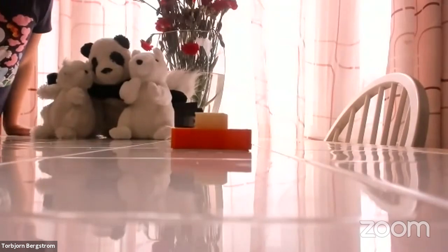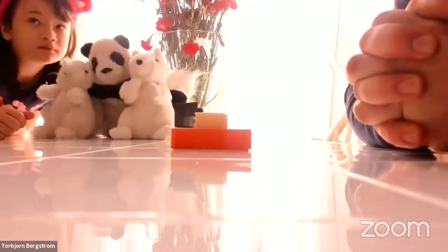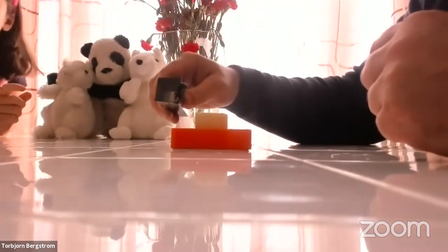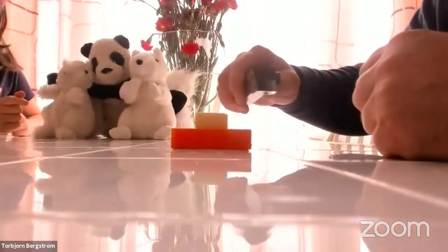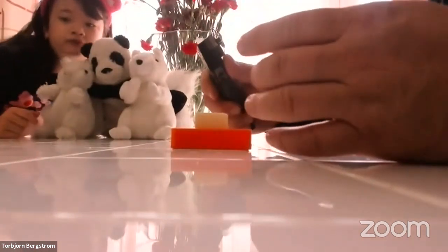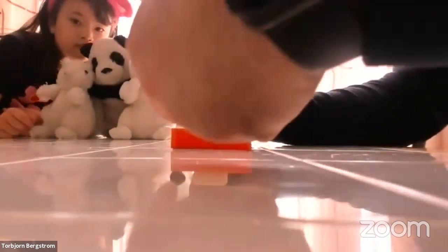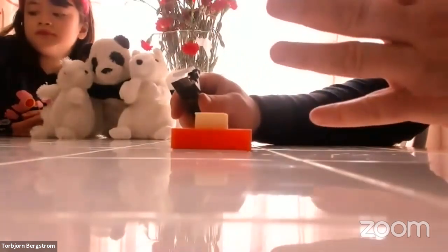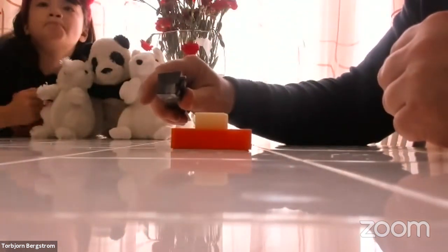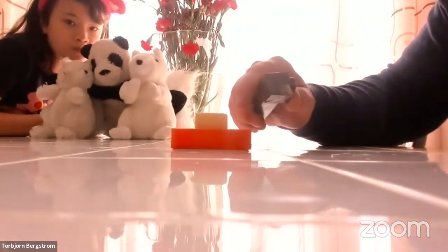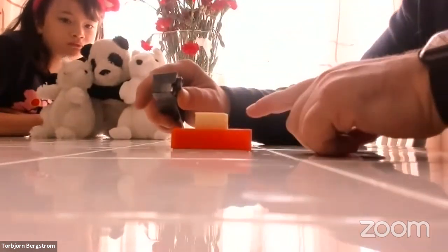All right, and you see Emily? Yes. Perfect. All right, so now when I move the tool up and down, I'm changing the uncut chip thickness. When I move the tool this way, this velocity that I'm moving the tool, that's actually the surface speed. That's the speed that the cutting tool is moving through the workpiece material. Now, normally we get that surface speed by rotating the workpiece. But since the cutting operation we're doing right now is really like a planing operation, the surface speed equals the feed rate. So the feed rate is going across here, the surface speed equals that. Normally the surface speed comes from the rotation of the tool, so don't forget that.